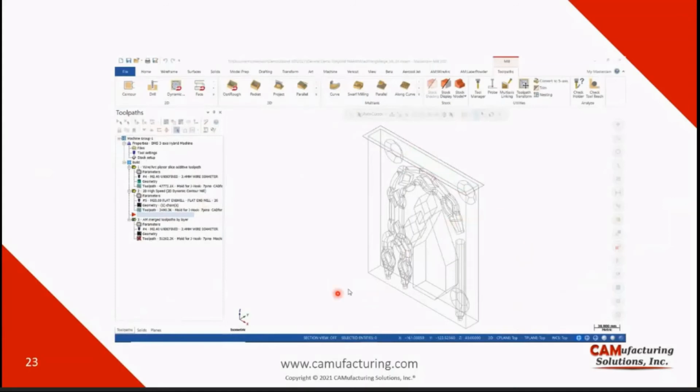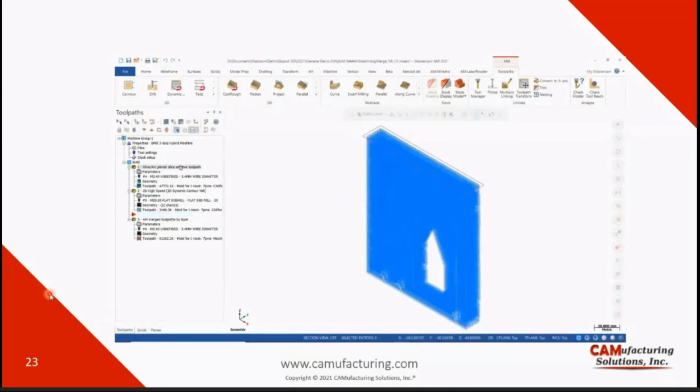So the result will be one layer deposition, decking, one layer deposition, another decking, one layer deposition, another decking. It means every time that you're depositing a layer, you're depositing it on a smooth surface, so it gives you a better result.